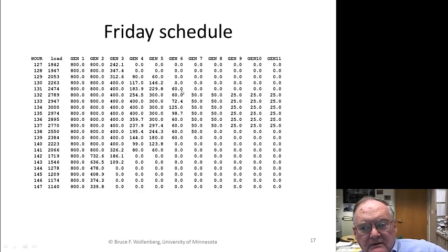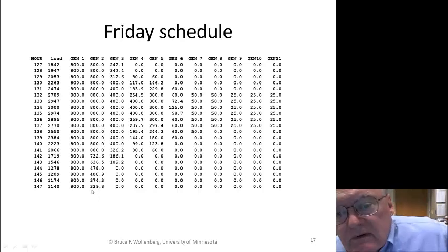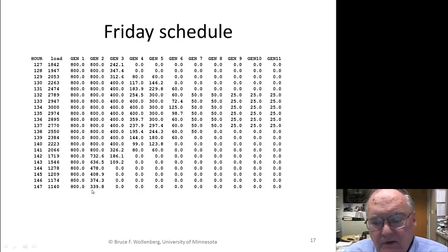Later on, I put on 6, and then I put them all on. So here I have a peak load, and I've got all the generators online. And then as the load goes back down again, it drops 4 units right here, and then starts dropping again 1 unit at a time until we get down to 2 units. Those are typical unit commitment schedules.